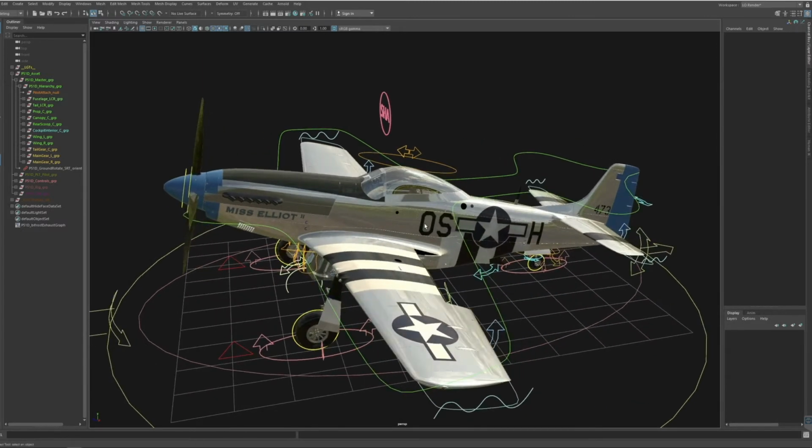However, as soon as you start to use procedural noises or anything that Maya can't display in the viewport, your object will usually turn either black or orange or some other color, because that's basically Maya's way to tell you that it can't display what is currently being fed to the shader input.